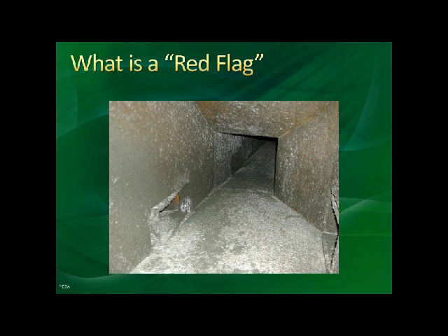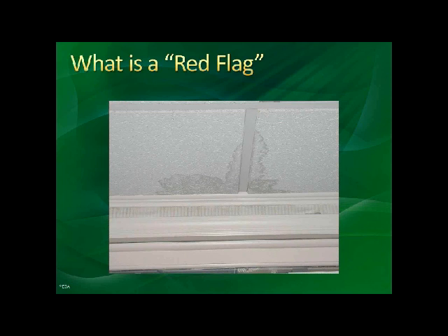Here's a simple water stain on the ceiling tile. At this point, this is an active moisture stain. Could there be mold above it? Could there be mold behind the wallpaper that's curled and the wood trim? There could be, but I must also inform you about protecting yourself. If you take on the liability to pick up that tile and look behind it, make sure that you have an intrusive agreement signed with your client in case that tile becomes damaged. Wet tiles are very, very, very brittle.